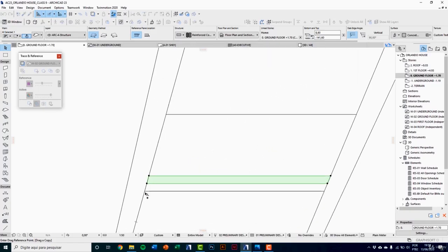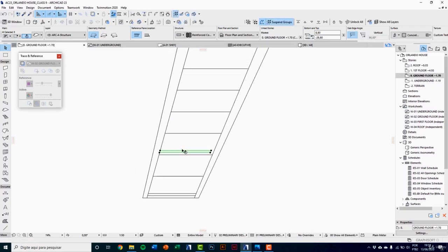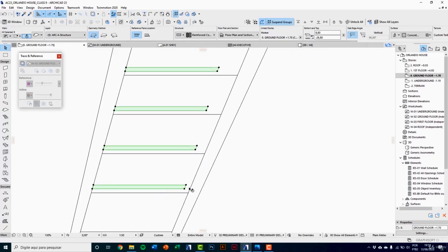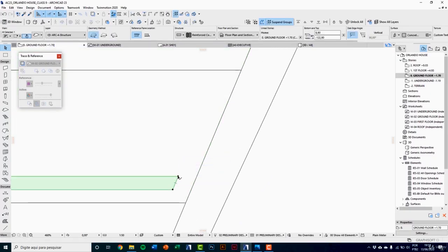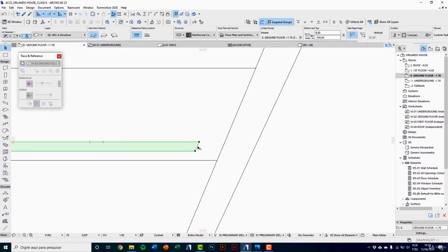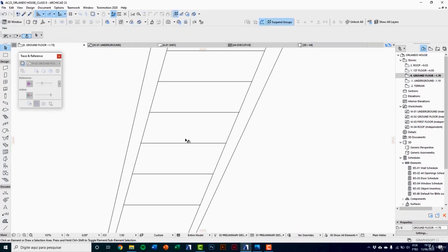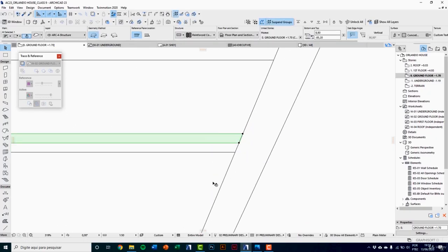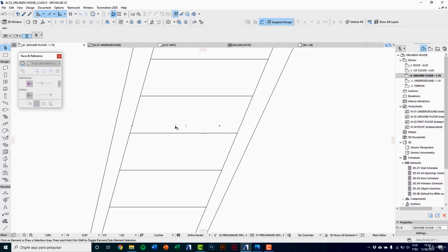I use the starting point as reference, click here, and all the work is just offset add for all these elements. Offset add. You can press the Tab key too, selecting these elements and adjusting offset.